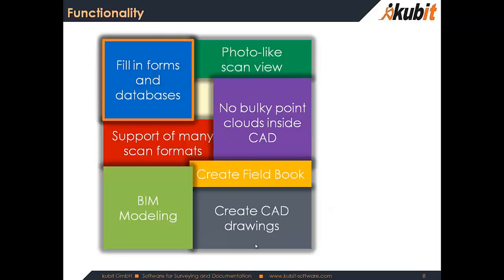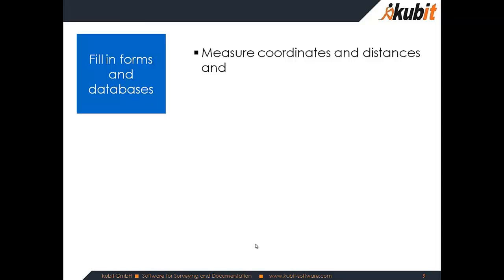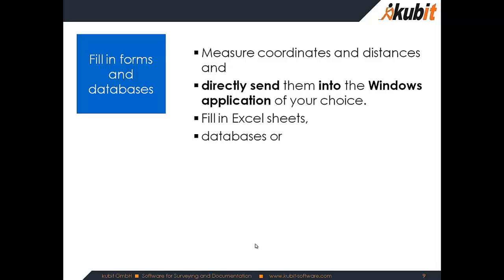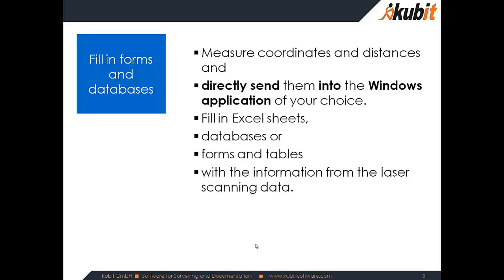With VirtuSurv you can fill in forms and databases. It works like you measure the coordinates and distances directly in the scan and send them into the Windows application of your choice. And this way you can fill in Excel sheets, for instance, or any database or other forms and tables with the information from your laser scan data.